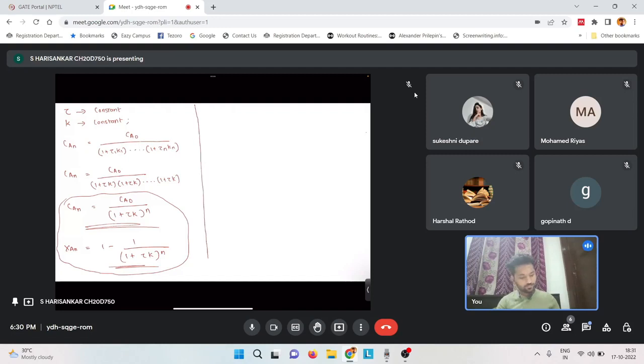I'll put you through this. So let's take two cases. So in one case we have a CSTR, to have better conversion. Fine. Not exactly, but you are on the right line. So I'll show you how. So let's take case one. We have a CSTR with our tau as, let's say, some 100 units, and let's take case two where we have four CSTRs in series.